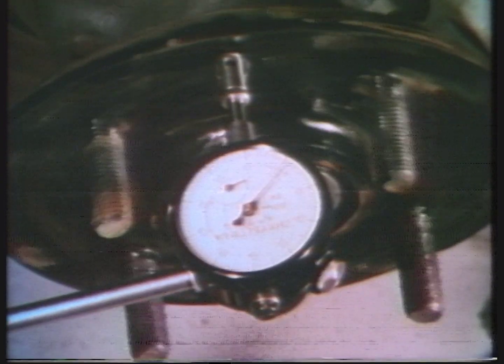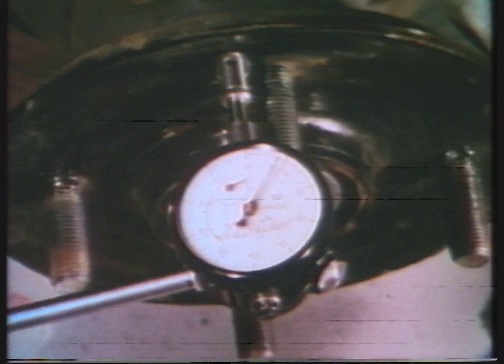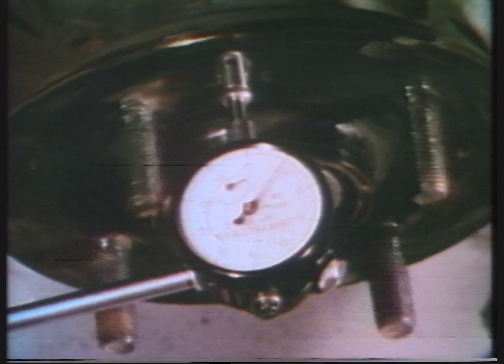The dimensional position of the gauge stylus is important to an accurate reading. Acceptable radial and lateral runout at the tire must be achieved. 3 possible causes have been pointed out in addition to tire eccentricity on the wheel itself. This is the most common cause. If the vibration remains, additional mechanical checks must be made.